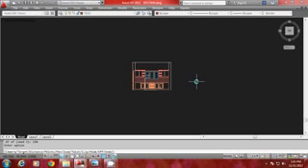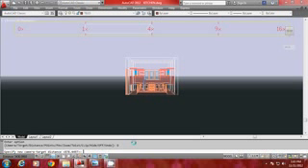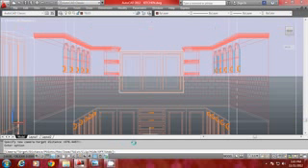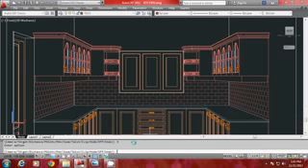But still I am in the orthogonal view. So if you want to get back to perspective, just go to distance option, type D here. Now it will show you the current distance separating the target and the camera. You can either just give an enter to select this distance, or you can give a different value if you want to vary the distance. So I'll just give an enter. So I just give hide. Now you have got a perspective view here.